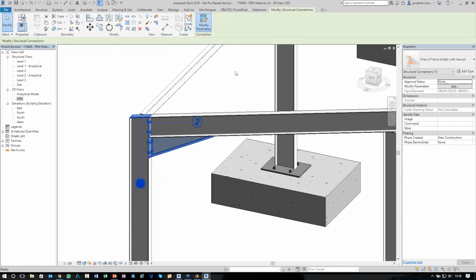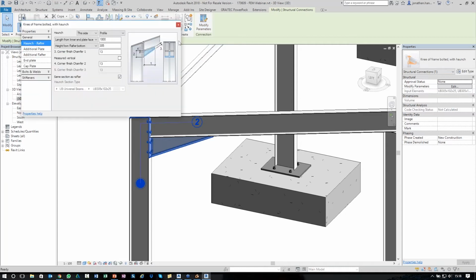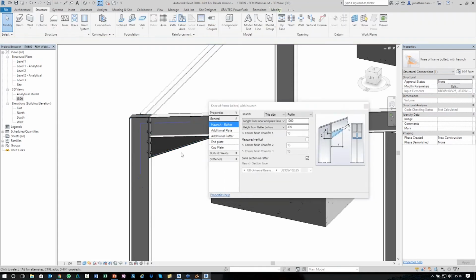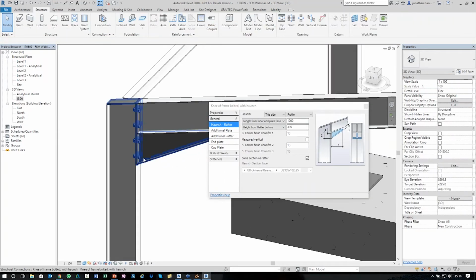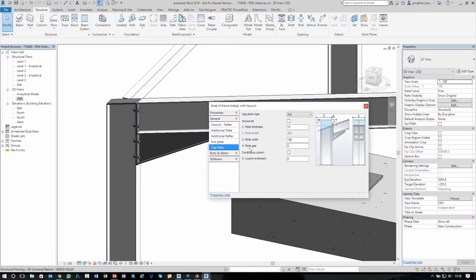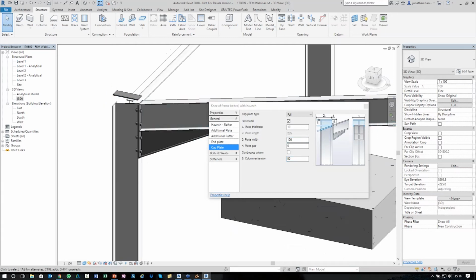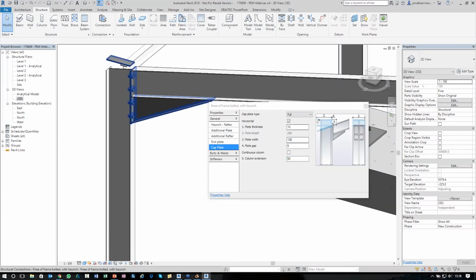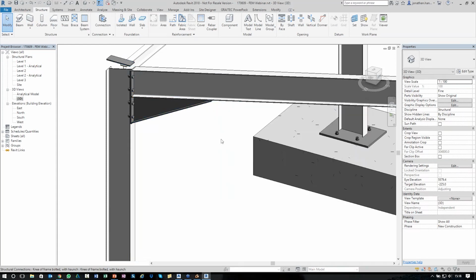You can create multiples. If we select this, I can go in, structure, connection, apply my apex haunch. So it can get quite quick as you get more and more used to the system. Again, modify the parameters of that. Stiffeners, I'm going to change that to none and none. The bolts are a bit tight for me, so I'm just going to go in and change it. I'm going to say that probably should be 150, just move it down a little bit in my system.